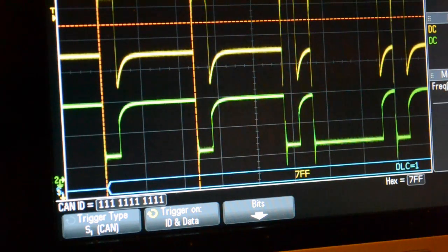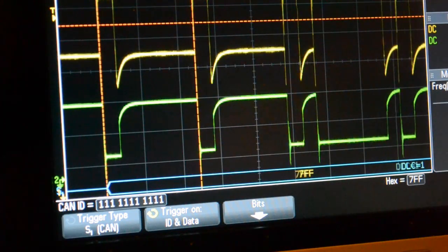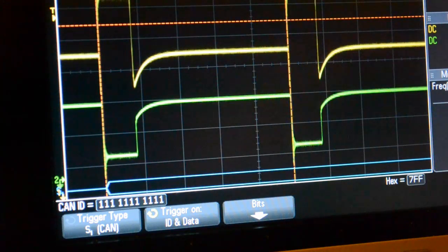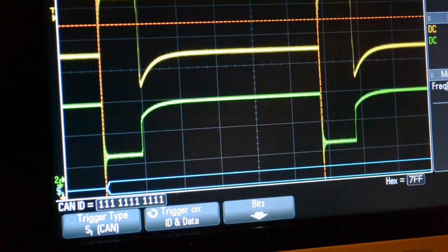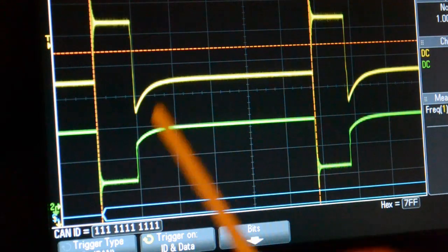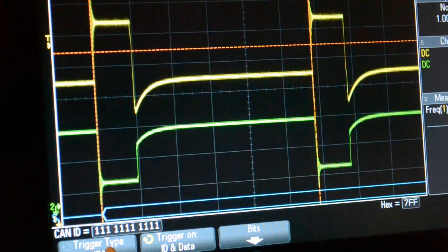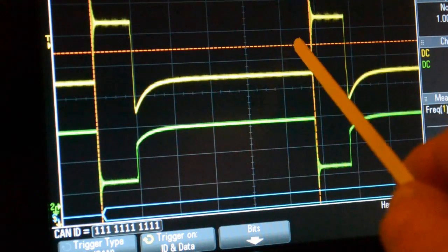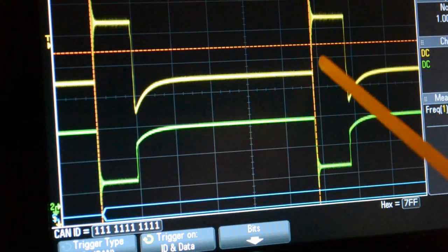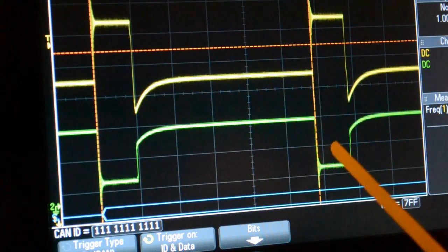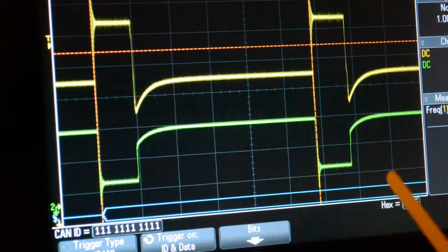So if I change the time base on this scope to fine, press this button, now on fine, and expand this out, you can now see the start bit is equal to 1 division. So that's the start. Then we're sending the string of ones down here. So look, 1, 2, 3, 4, 5. If I didn't send a 1, all of a sudden we've got a 0 there. So that's the stuff bit. That's not counted in the frame. Nevertheless, it's in there.